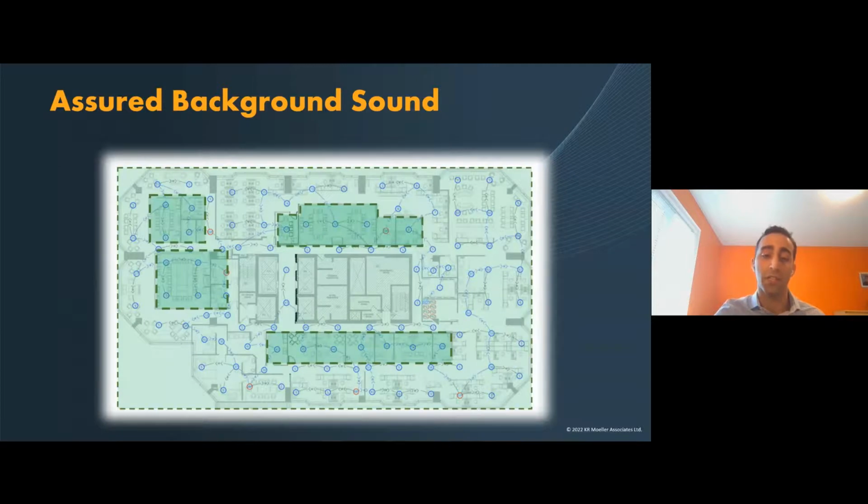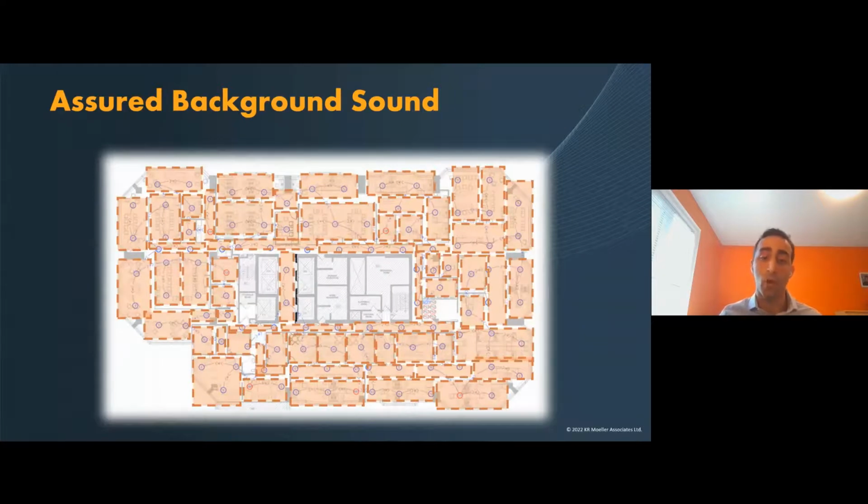Fast forward to the 21st century. Technology is no longer a limitation, and advances in electronics allow for decentralized architectures and for addressable components within a networked system, meaning there are no barriers to specifying small zones or to installing them. The ability to deliver localized control of sound by decentralizing the generation of sound rather than requiring long runs of cable is now an affordable reality. The final hurdle, field commissioning, is also overcome using software to automate the tuning process. This is able to reduce the time required to tune a zone down to under a minute, 15 to 30 seconds to be exact. But more importantly is the ability to tune with far greater accuracy and precision than is at all possible via manual methods.